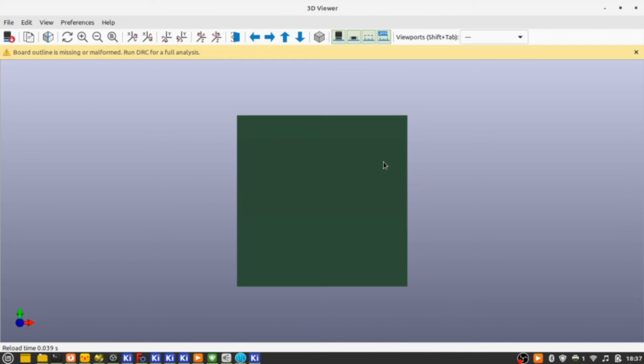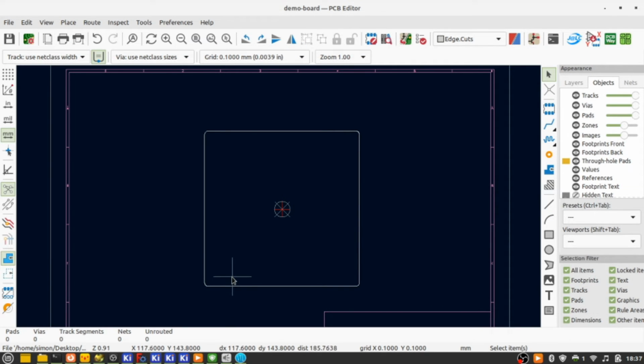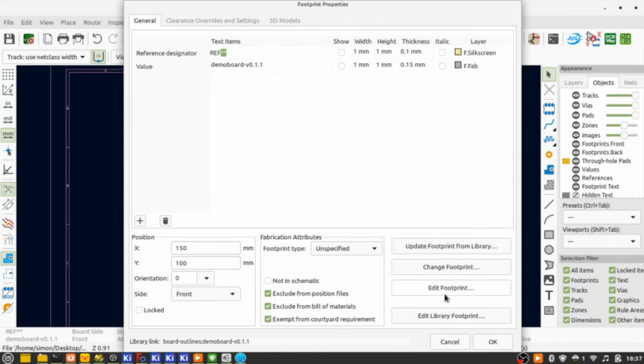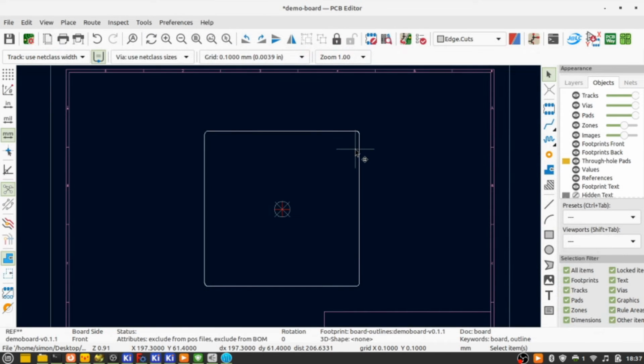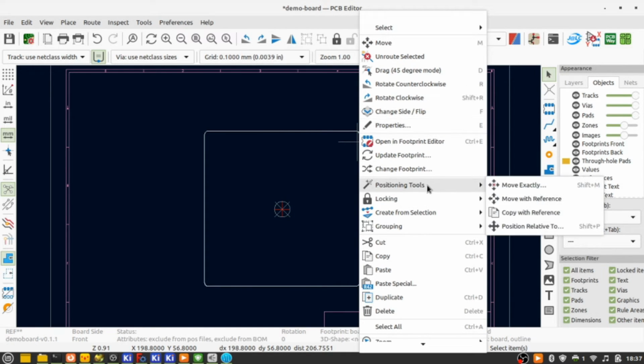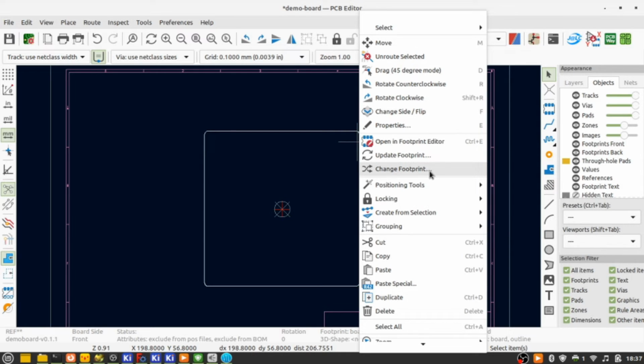Look at the, oh, okay. This happens when it imports it twice on top of each other in the footprint. I don't know why it does that. We'll do edit library footprint. We want to enter into the group. Yep, select one of them, delete it, keep only one. Save again. Again, I don't know why it does that. It does that with DXF too, except DXF tends to have some additional problems. On KiCAD 7.0.0, there were some additional problems with DXF that there just weren't with SVG.